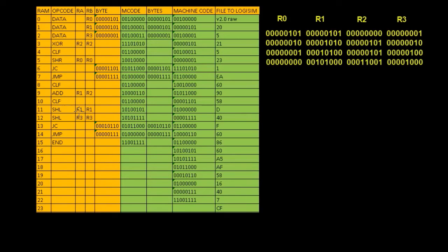So if we've shifted this left, the last thing to do now is we shift the value of R3 to the left. Originally the value of R3 had a value of 1, and we shift it 1 to the left, so now it goes to this point here. And then we've got to check and see if the carry has been set. If this had actually been all the way along to point 8, then the carry would be set whenever we shifted left, and we'd know we'd be at the end of the program.